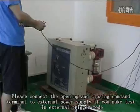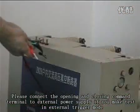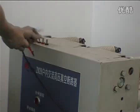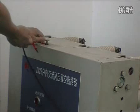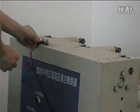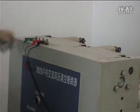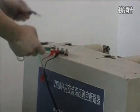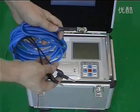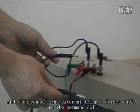Please connect the opening and closing command terminal to an external power supply if you make a test in external trigger mode, and then connect the external trigger detect cable to the command coil.